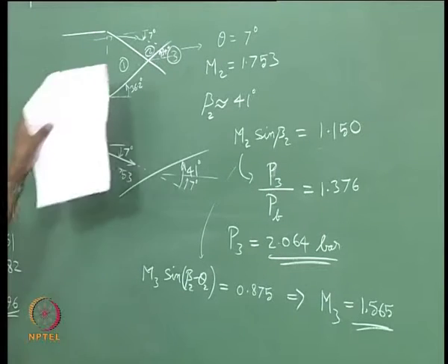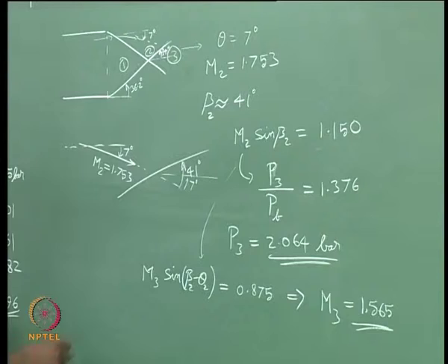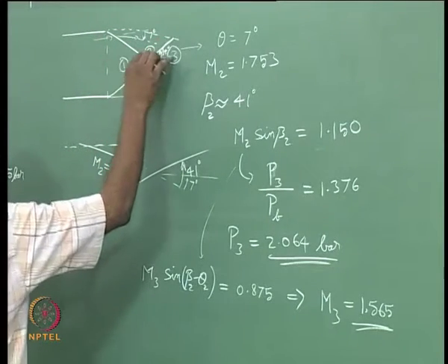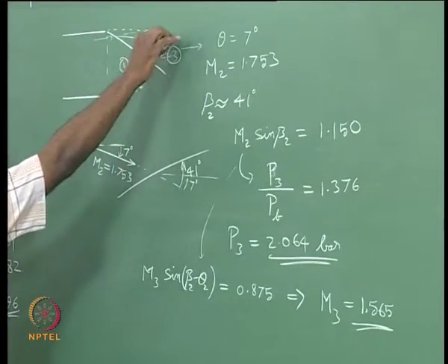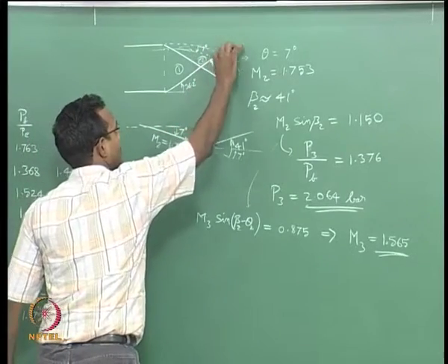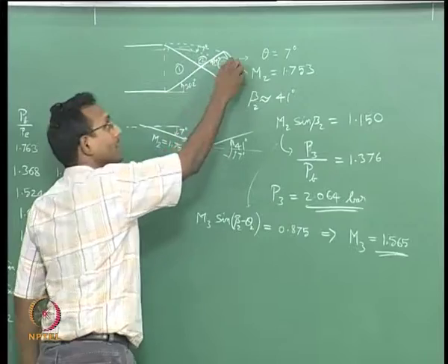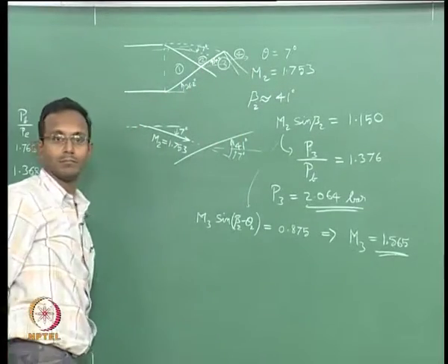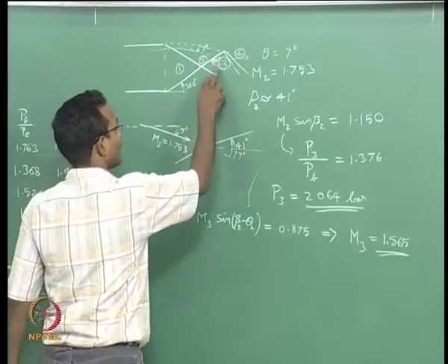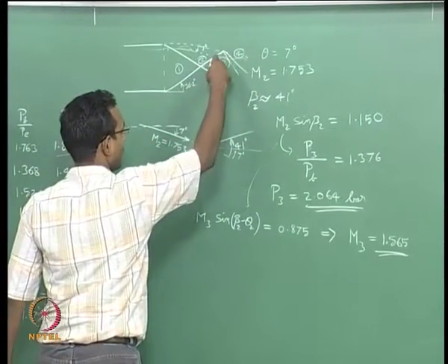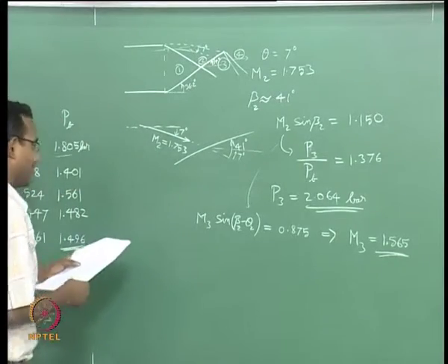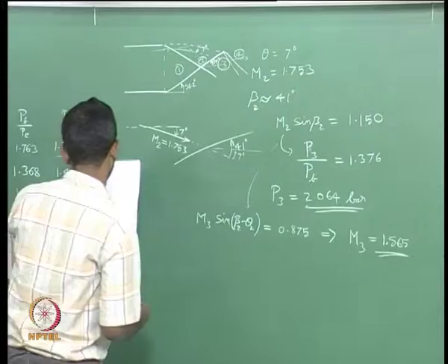Now, we want to continue the calculation even past this point. Now, I know my dotted line, if I extend for my jet boundary, when the shock reaches there, after that there has to be some expansion fan here such that the pressure in this region 4 is same as my back pressure, the outside pressure. So, from 3 to 4 I need to have expansion fan. Okay. Simple calculation after that. We know expansion fans are easier to calculate.